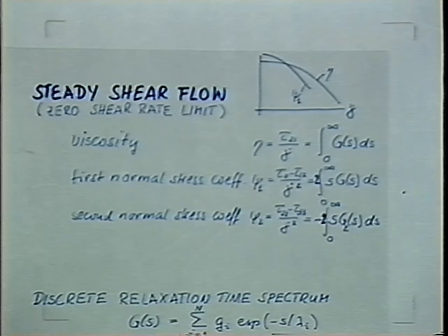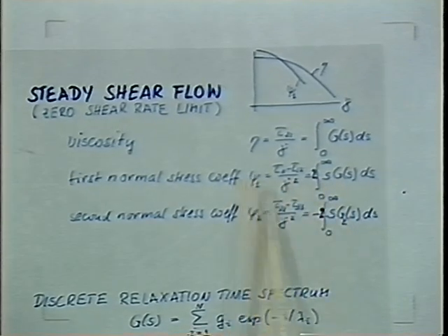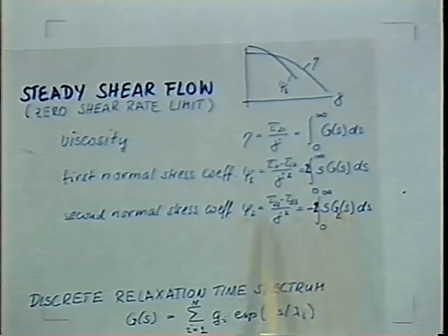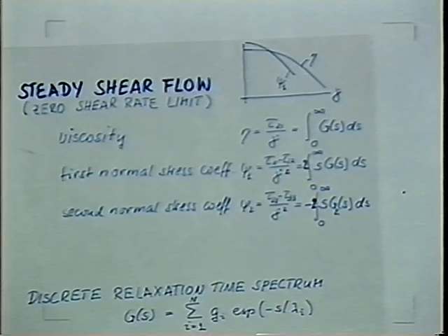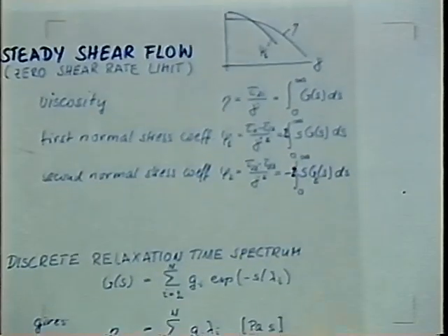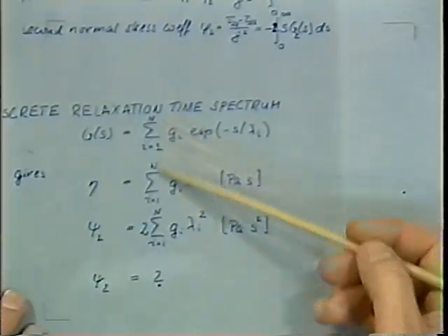So by using a proper strain tensor, we are able to model the first normal stress difference, model this contribution, and even that contribution if we're able to distinguish between all of that. You can calculate these with the continuous spectra, and you can with the discrete spectra, and you also can calculate those with continuous relaxation time spectra.